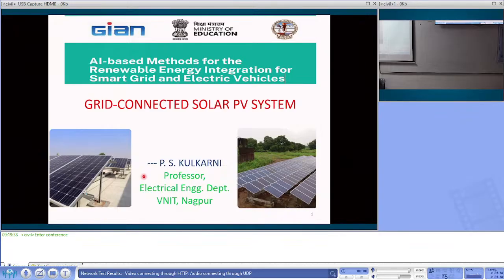After several years, when the course was organized, they said that now the output is only 1200 watt. The factor which is very important that brings this out is degradation. So degradation factor is very important when you carry out analysis.